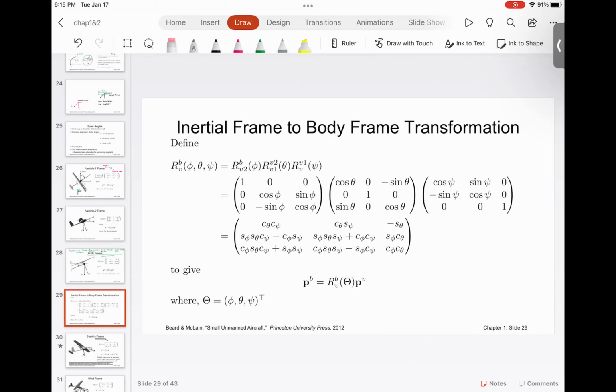A teeny tiny variation in theta gives you the approximation sine theta equals theta and cosine theta equals 1. So when you are propagating the rotation matrix throughout the solution at every millisecond, you can use the approximation, and for that computation only, these rotation matrices can be commutative.